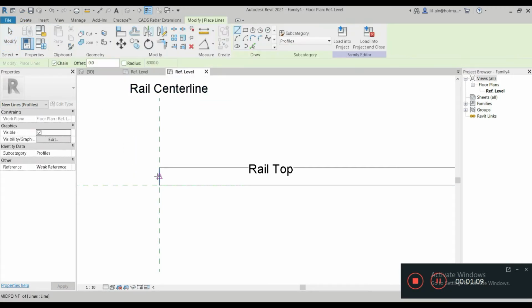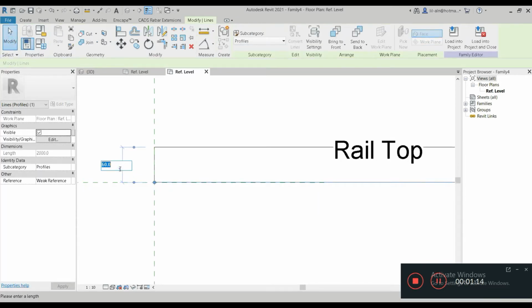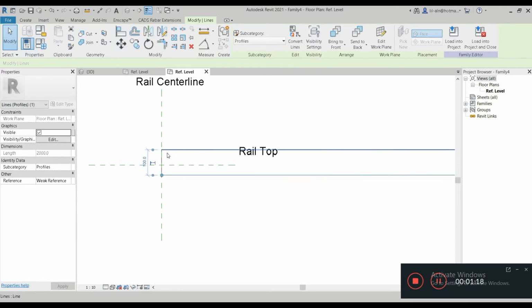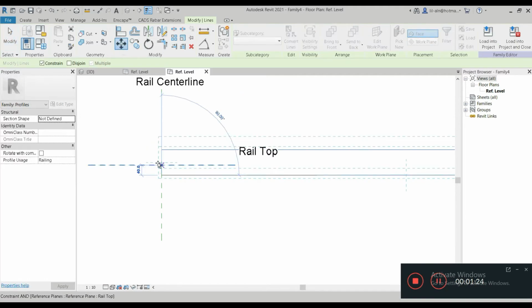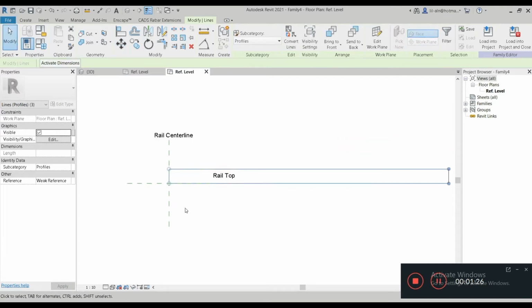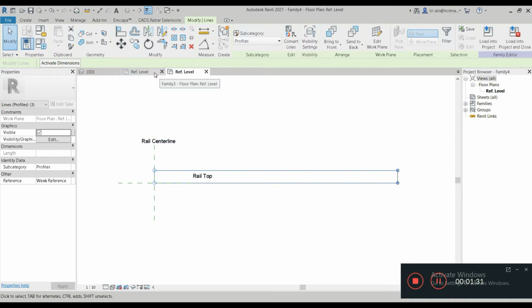So when we're making the families, we would again have to make sure that the width is set to 2 meters, and the depth can be around 100 mm. That's fine, or something close, it doesn't matter. So this is usually what the thicknesses are, but the width is important, which is 2 meters in this case.